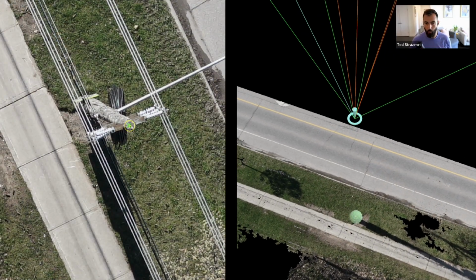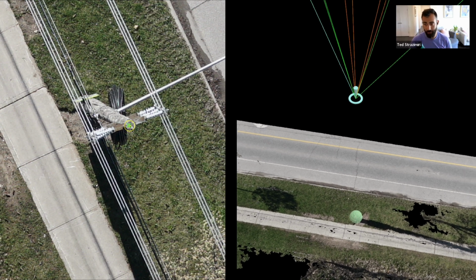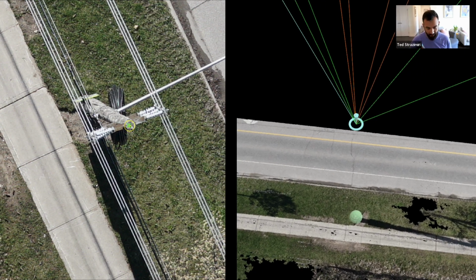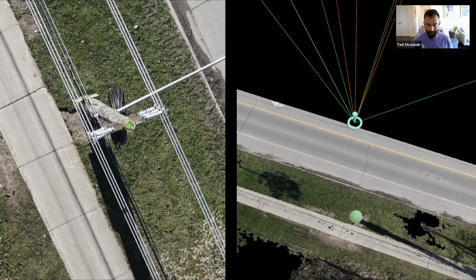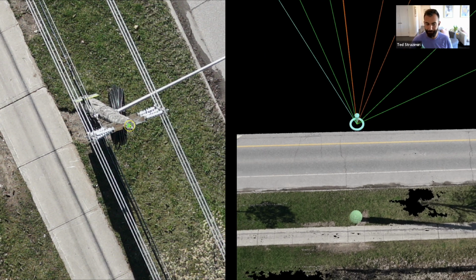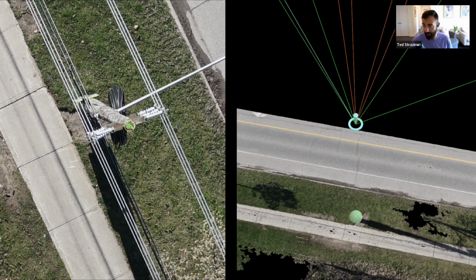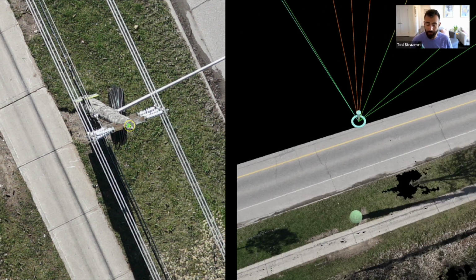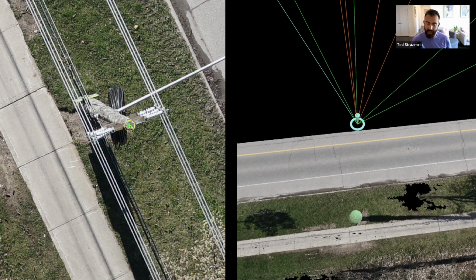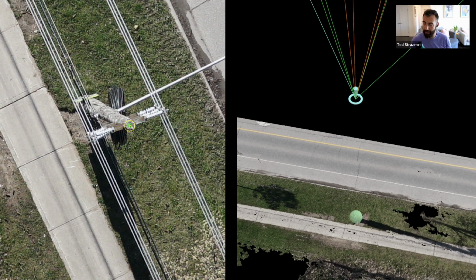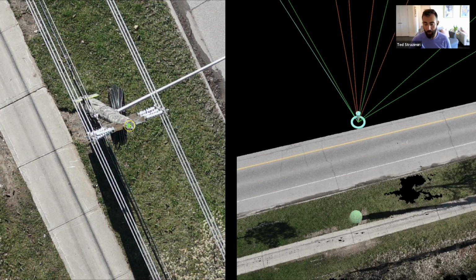Another situation where you begin to see the shortcomings of photogrammetry, and trust me, I love photogrammetry. I'm not knocking photogrammetry. It's definitely my favorite way of capturing reality, but it suffers when it comes to thin structures. So you can see this distribution pole on the left, and that's very clearly there. It's there in many photos. However, in the point cloud, it does not appear. It was never reconstructed. And that's because it just doesn't have that much area with respect to everything else on that image to be matched over and over again and selected to be reconstructed.